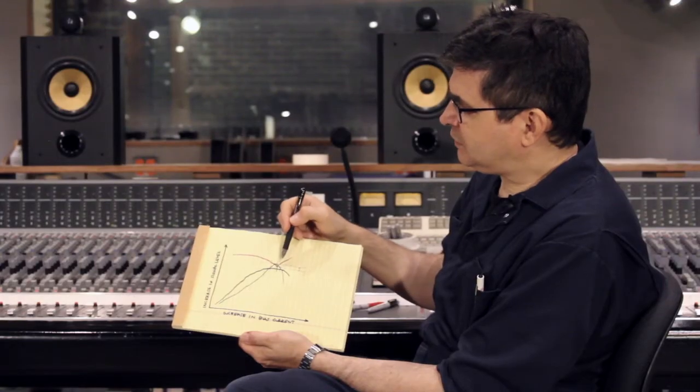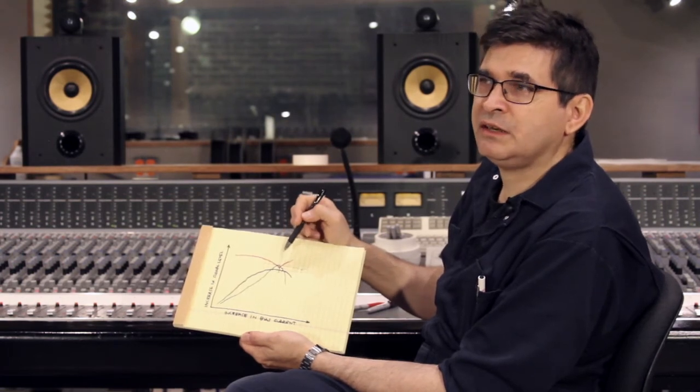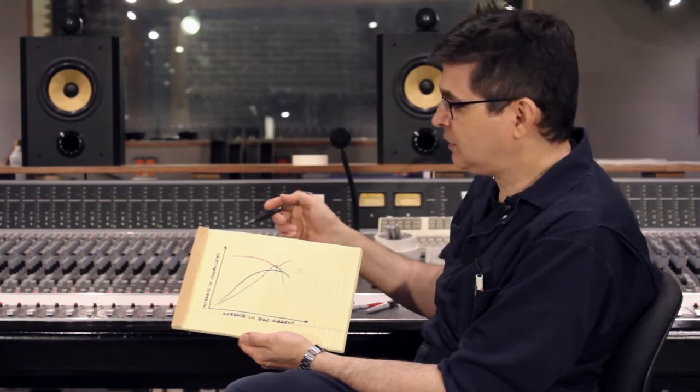And that can be used with any tape on any machine. That is, if you find yourself with a tape machine and a reel of unknown origin and you need to record on it, you don't know who made the tape, or you have no access to the information about the machine that would describe the head gap, so you couldn't find a published spec for it. Using the noise and distortion characteristic of the machine is a way to find optimum bias on that machine with no other tools. If you have an oscillator and a tape machine, you can find the optimum bias point for any tape.